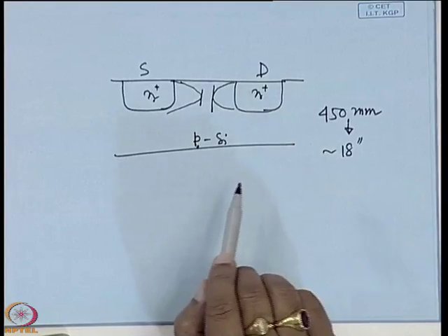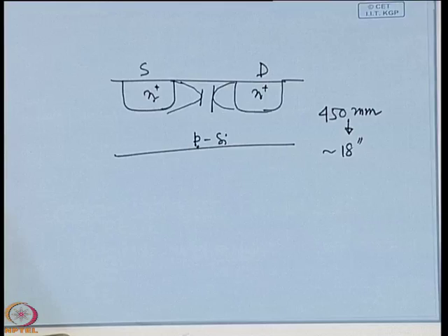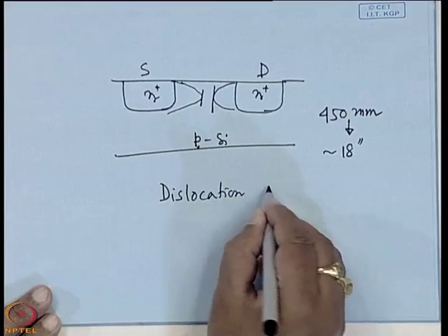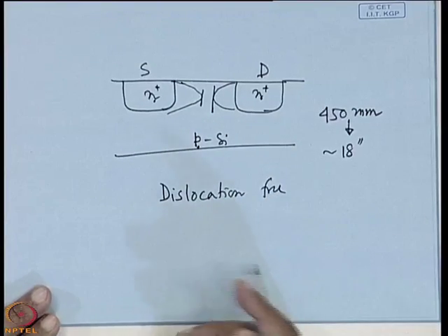So, the silicon crystal growth is becoming a very hot subject for the future generation IC manufacturing technology also, because unless you can provide very good type of material. In this case, not only the purification, another thing is that the diameter, not only it will be large, at the same time it will be dislocation free. This is another term which is very important, dislocation free. What is dislocation? That is a kind of defect.